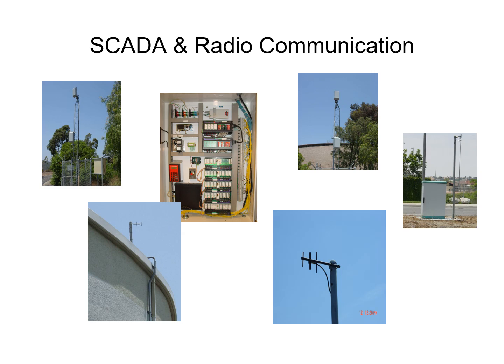All right. SCADA and radio. So how does that information make its way back to you? It's through these radio communications, otherwise known as telemetry. You will see these little antennas on top of reservoirs or at facilities, and it's usually angled towards some kind of a repeater. Those repeaters will take in that information and then send it on to some kind of controller. You've got an image of a SCADA cabinet. You've got different types of antennas here, but this is just some of the stuff that we have out in our system at VID.